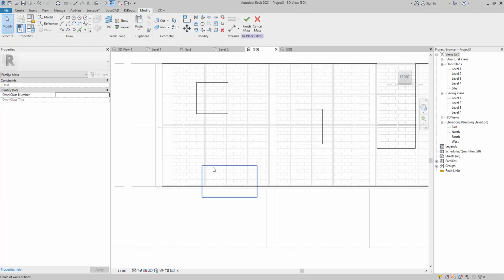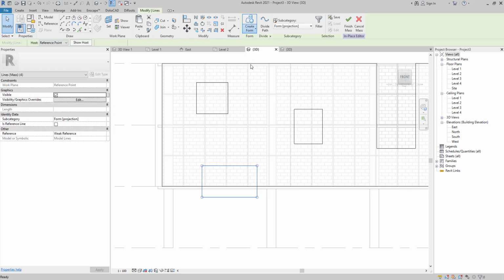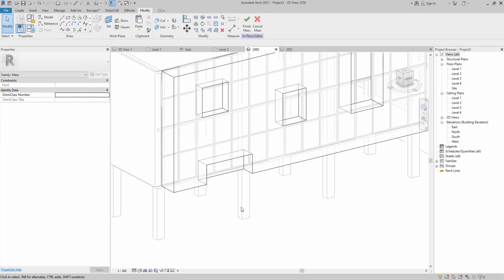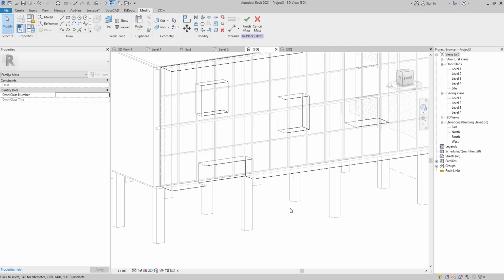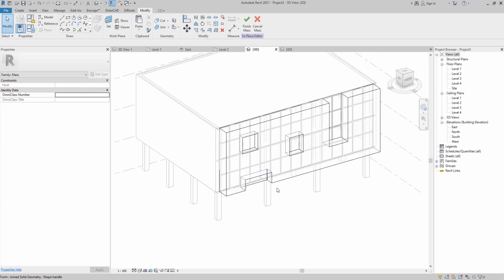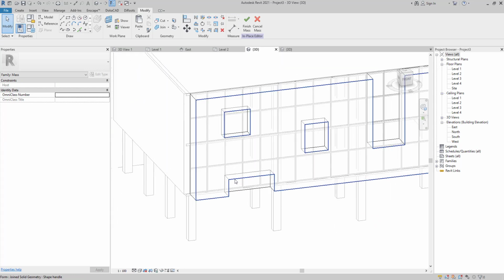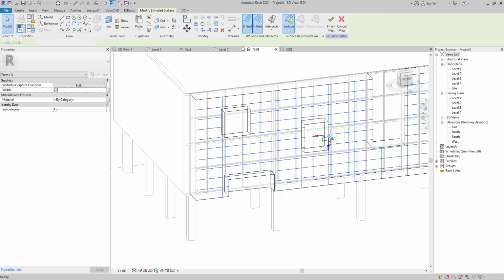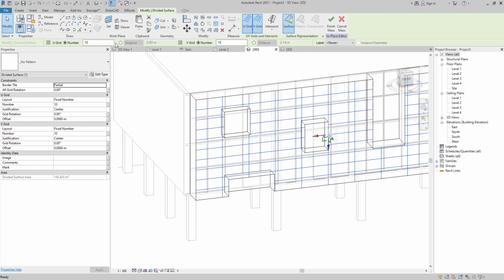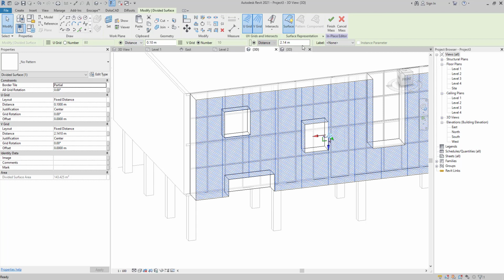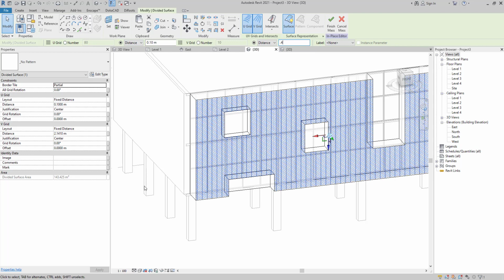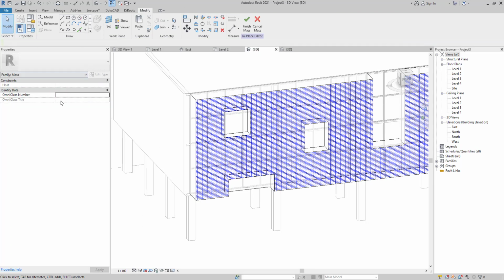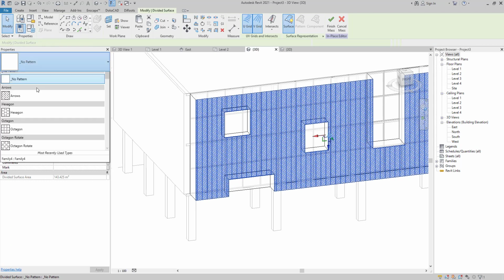And I can go and select create void form. So we are going to have this kind of void element here. So we are going to select our face divide, and we are going to put the numbers 10 centimeter, 40 centimeter. So there is one more way to fix it, which I'm going to show right now.